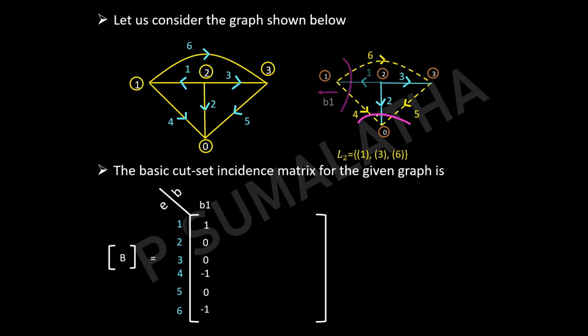The direction of the cut set will be the same as the second branch, that is the downward direction. So this direction is entering into the node. Whichever elements are involved in the cut set, that means 2, 4, 5, if all the lines' direction is towards the node, then all carry positive 1.